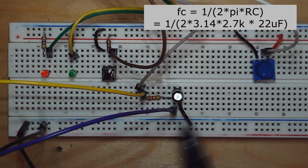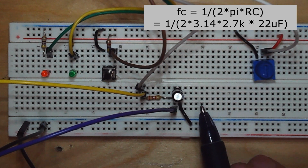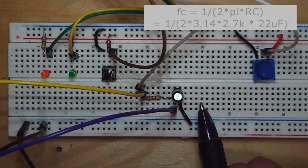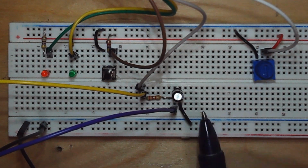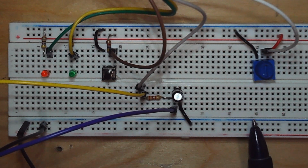Okay, so the resistor and the capacitor give us that low pass filter. The equation for the low pass filter is that FC, the corner or cutoff frequency, is equal to 1 divided by 2 times pi times the resistance times the capacitance. Okay, so now that we have all of that together, we can try it out.